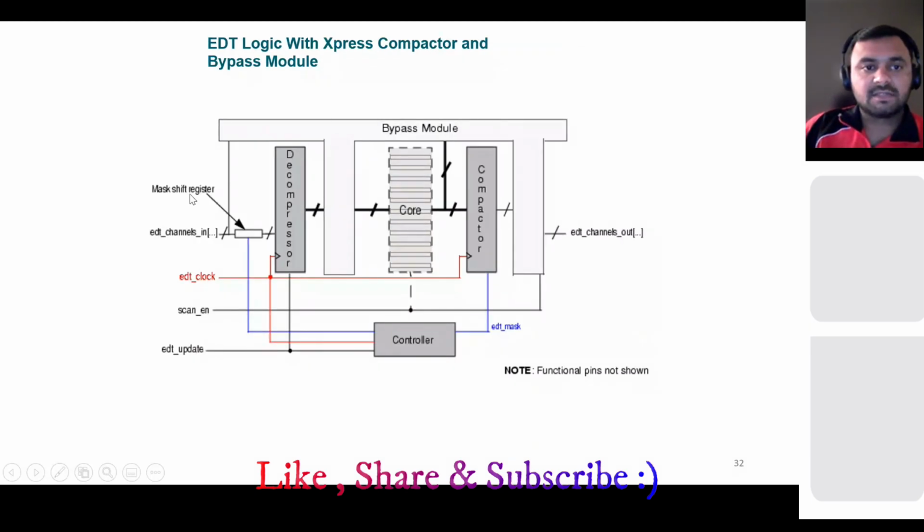Here you see the mask shift register. Between the last slide and this slide, you see only this mask shift register and there is an EDT mask signal. What happens is, suppose you want to mask a chain because there is a problem in it. You created 40 chains, and on the output of some chains you are observing X, because it's coming from some analog blocks or memory blocks which are not controlled, and they are throwing X. You need to mask that, because in ATE you only have 1 and 0, you don't have X and high Z. So for that you use these mask registers.